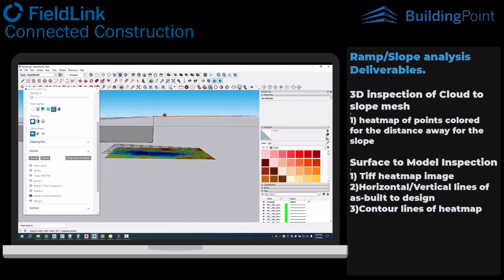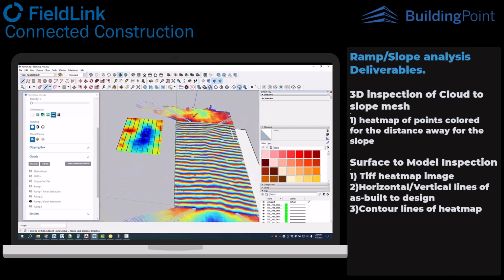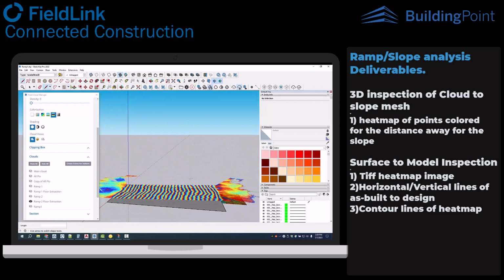But usually what I like to do, because I think it's a little more accurate, is create a line with the arctangent of that degree slope. So I've already done that and created this line, I believe, as an arctangent of like 2.7, but you can see that's about 5 foot and 5 inches, which corresponds to about a 2.7 degree slope, which is what we saw. So usually what I'll do is I'll create this line and then bring this up.